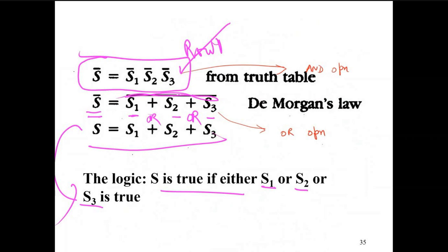Now, is this problem as simple as what I am presenting? Take a real punch press. Yes, there is a hydraulic pump that is going to put hydraulic pressure down, at 40,000 psi. They are built solid, but there are hydraulic lines which can leak. You want to put a leak detection sensor by monitoring the pressure. If it is supposed to be 30,000 psi, you want to make sure it is plus or minus a few psi. If it drops to 10,000 because of some leak, you're not going to have a quality pressing. Probably useless and to be thrown out as garbage, wasting material. So you will put more sensors to measure the actual pressure.